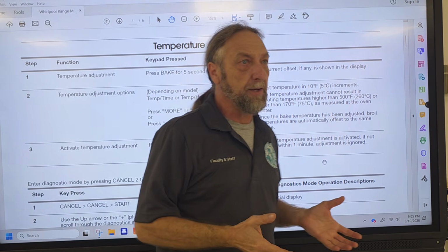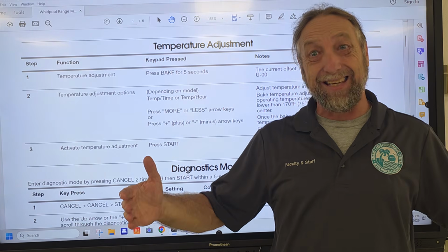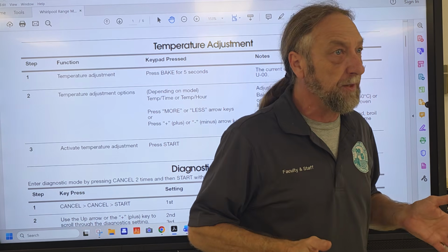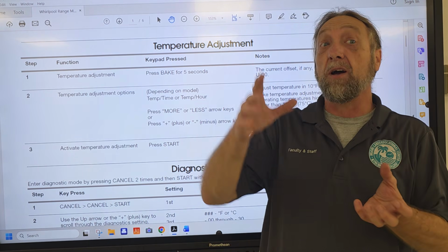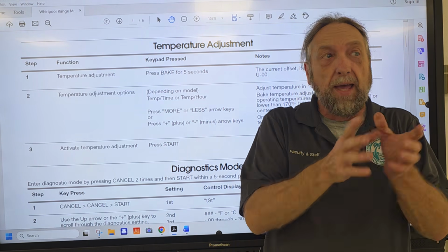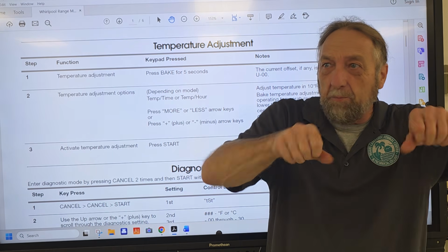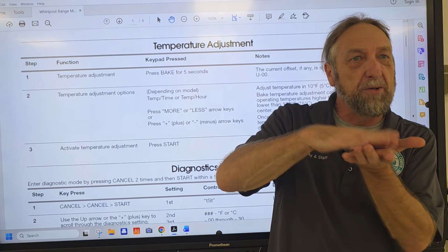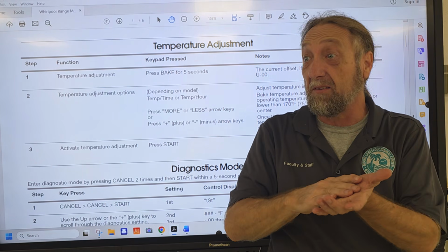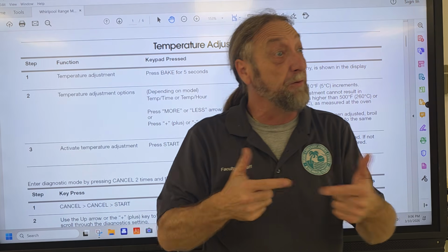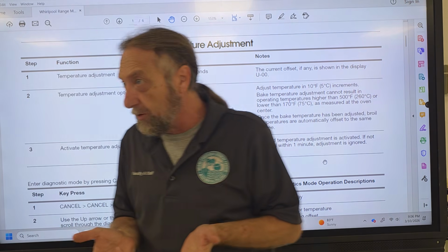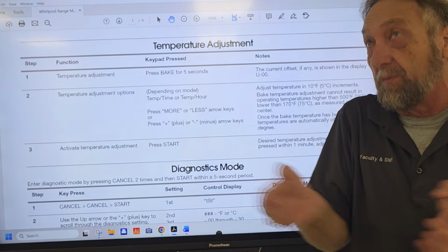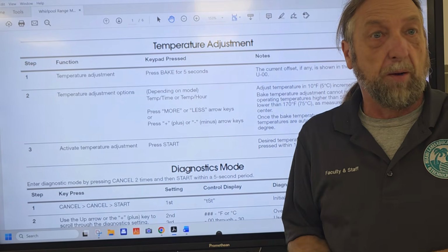When we cook in an oven, we don't want the oven to be totally sealed. We want airflow and air circulation so that everything cooks evenly, okay? Now, if a customer takes the burner out and takes aluminum foil and puts it in the pan and puts the pan back and plugs the burner in, what happens to the hole in the middle? It's blocked. So now you cause uneven temperatures in your oven and you get poor cooking results. That's why I'm telling you about the vent, because it's important for proper cooking.